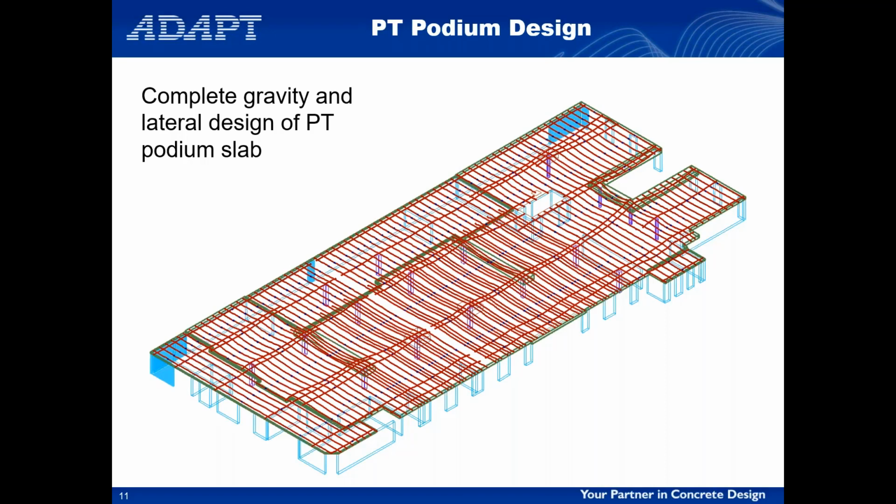The big difference will be that some of your post-tensioning from the podium will go into your foundation as opposed to being available as pre-compression in your slab. So the PT design is pretty straightforward.